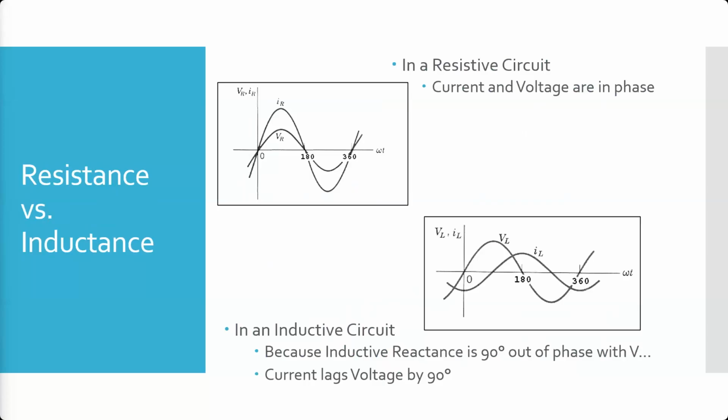The inductive reactance is going to be out of phase. So this original voltage, now we're just showing inductive reactance is I sub L here. And that inductive reactance is formed by those eddy currents acting back on the coil. And when you sum it all together, you get that impedance, that change in impedance.